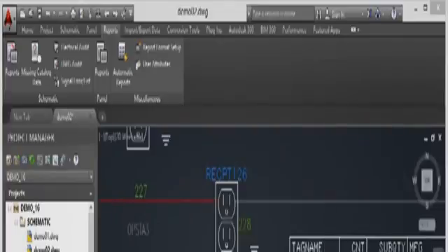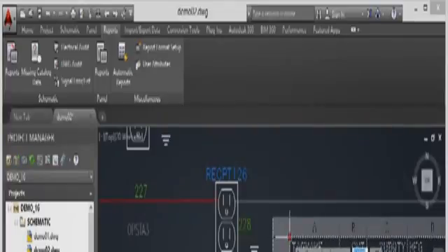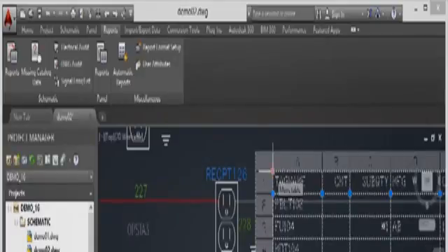It is an AutoCAD table, as you can see there, and I can very easily, if I zoom in real close, see the information in the table. Click on it there. I can click on this grip here and I can move that table around the drawing as I see fit. Now it does clash with some wires there, as you can see, so I'll just hit escape a couple of times. Double click on the wheel to zoom extents. And that's how you insert your reports into your AutoCAD electrical drawings.